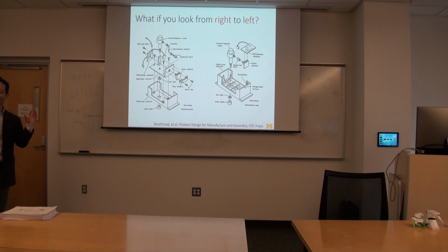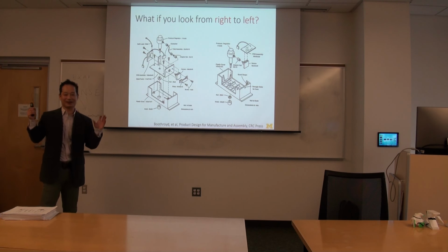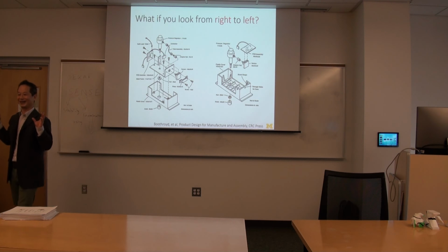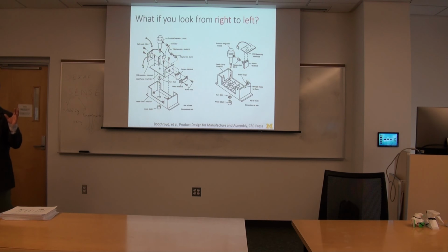What if I really have to make it so that maybe deep drawing and sheet metal bending is the only process available to me? Obviously I cannot make this geometry. I have to do something, maybe do that. This indeed was really the natural design, at least in these parts, natural geometry suitable for sheet metal bending.